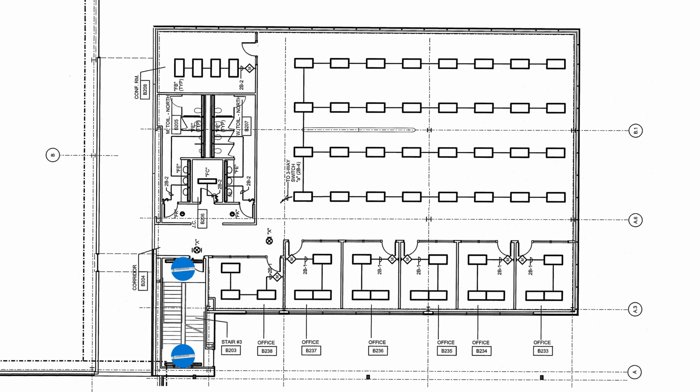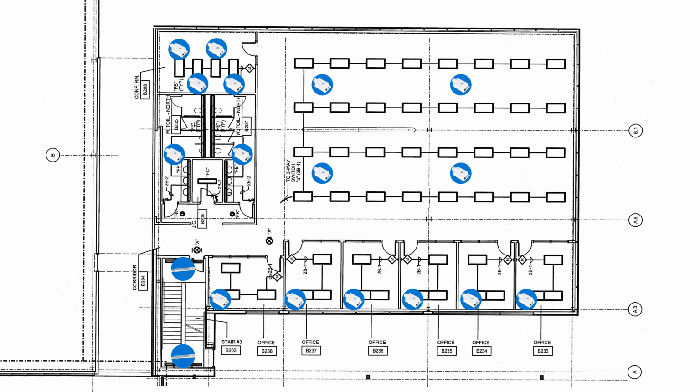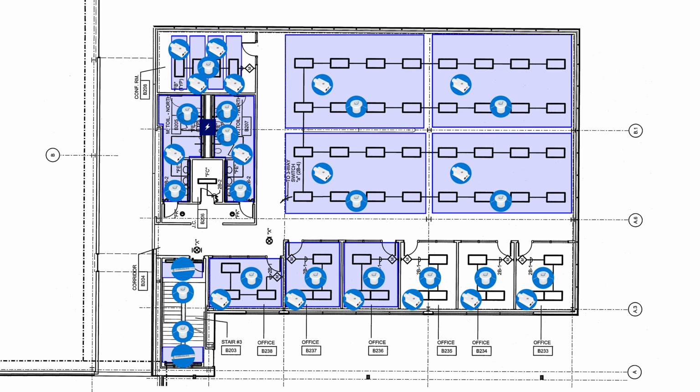At this point, we'll add back in the smart drivers, advanced load controllers, and sensors in the stairway and office spaces. You now know that the shaded blue region represents the switched power coming from the fixture control device in that zone, and that the sensors should be placed as close to their design placement as possible. Finally, the switches are placed in the design for areas requiring switch control, along with the Amatis border router, known as Amber for short.